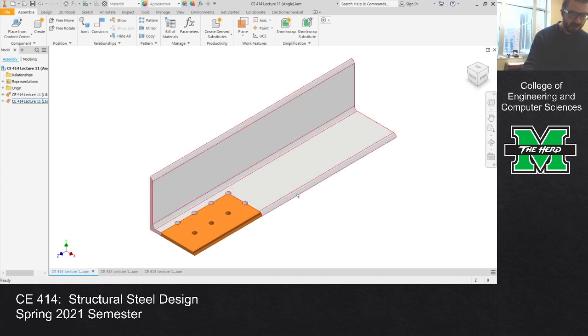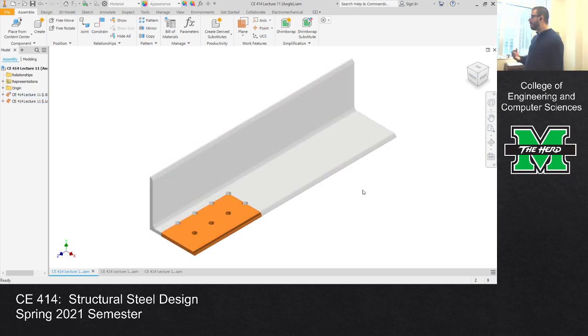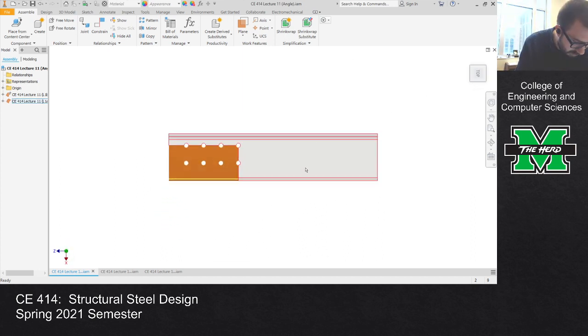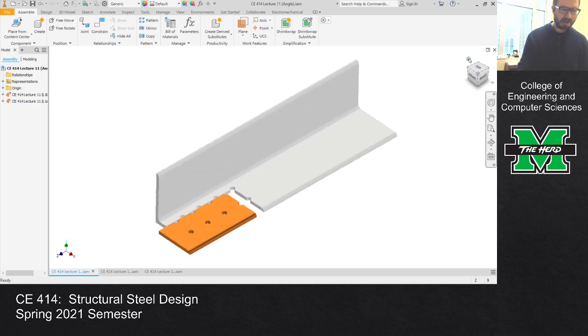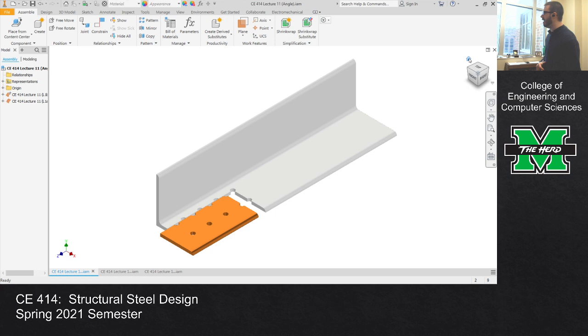Because the alternative would be, instead of this little block here, it's ripping through all of this over here. And if I'm thinking path of least resistance, what's the smallest potential block that would cause this member to totally separate? It would be this one, because if I look at it on the top, really what we're having is something like that going on. And so it's just sort of sliding off from that connected face. Does that make sense?